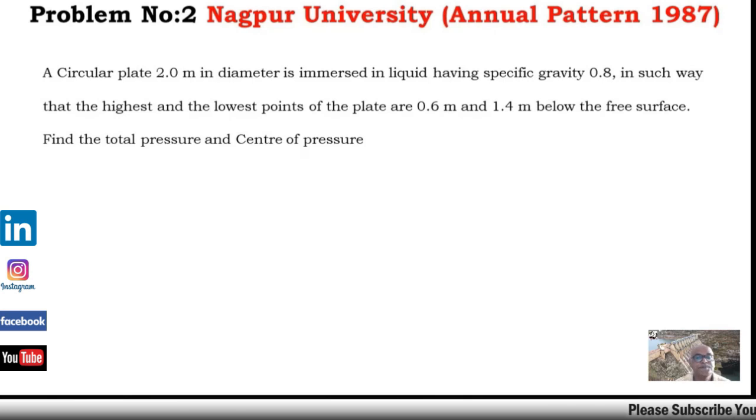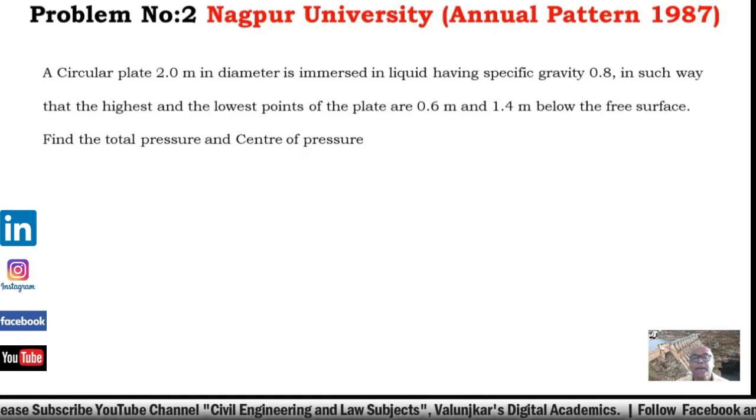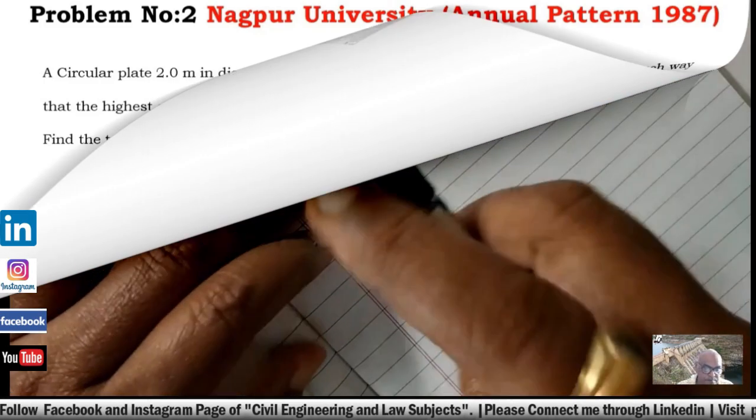Now problem number 2. I'll read out the problem. A circular plate 2 meter in diameter is immersed in a liquid having specific gravity 0.8 in such a way that the highest and the lowest points of the plate are 0.6 meter and 1.4 meter below the free surface. Find out the total pressure and the center of pressure. This is the case of an inclined lamina, because two elevations are given, 0.6 and 1.4 meter. So let us have the solution here.